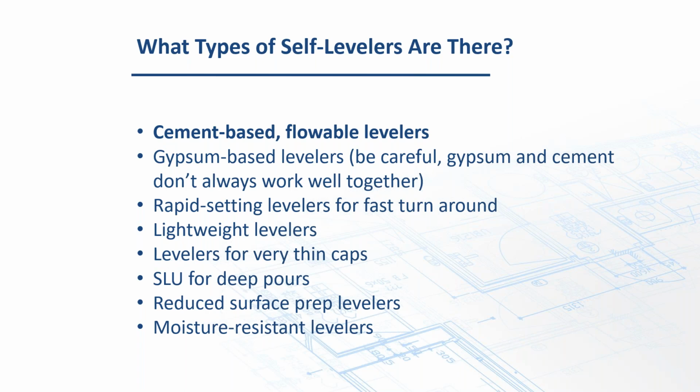Rapid setting levelers, so if you have to get on the project a little bit quicker, typically you can tile in 3 to 4 hours in most levelers. There's lightweight levelers. We get asked about these all the time in remodels, especially old buildings, where they don't want to put a lot of weight on the top. So a lot of times you get lightweight levelers. Levelers for very thin caps or just a skim coat, if you will.